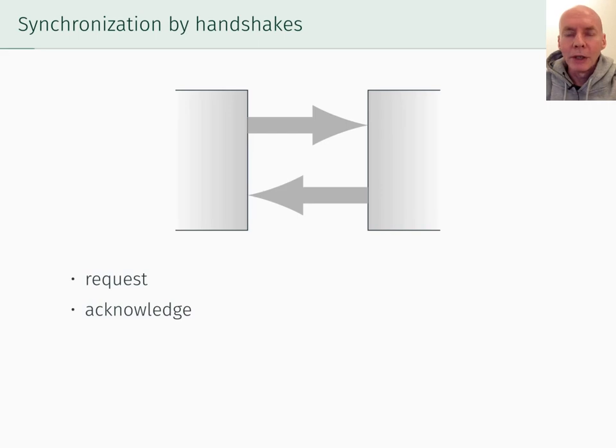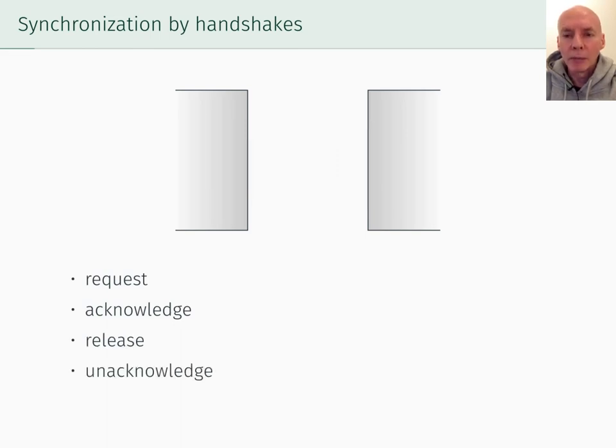But then if these two circuits ever want to do another handshake, they can't raise them again because they're already raised. So some would advocate a protocol whereby at this point the one on the left lowers the request line and the one on the right lowers the acknowledgement line. Then altogether 4 events have to happen for this handshake to complete, and it's called a 4-phase handshake.